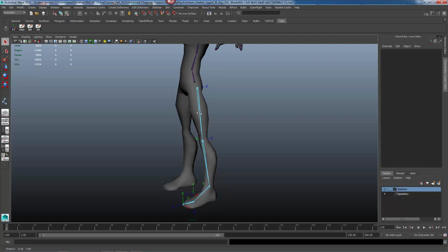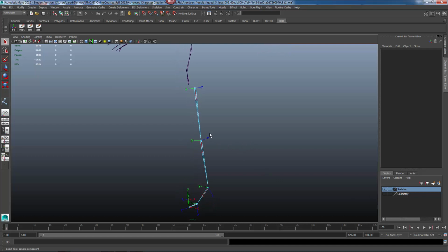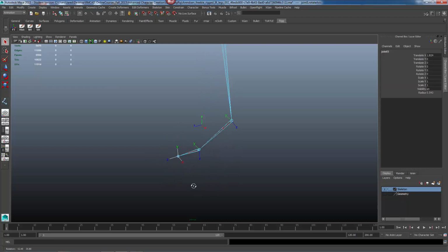So what we're going for, now I'll click V for my geometry to hide my geometry, is that X should be pointing to the child, and that's just the way that we're doing things in class. X points to the child, so this X is pointed there, there, and there, and any end X joint, like this one, we're going to rotate this, and I'll hit E to evoke my rotate tool, and I drag marquee around those because it's easier to select them.